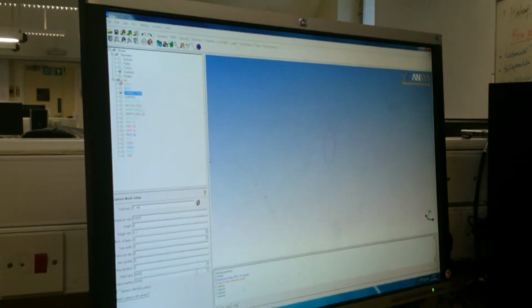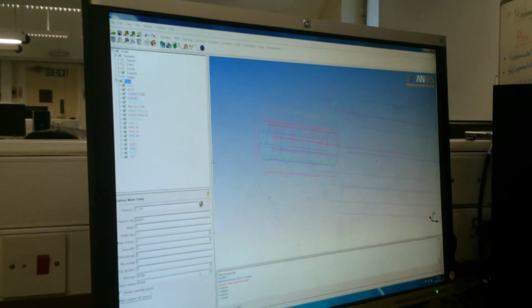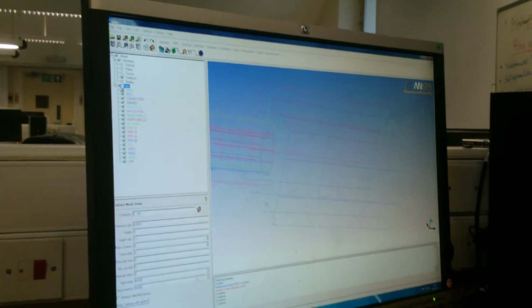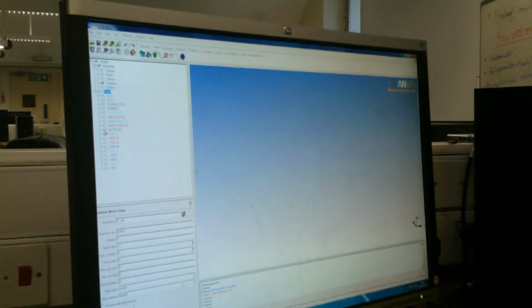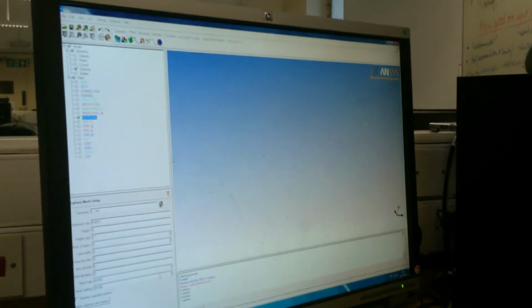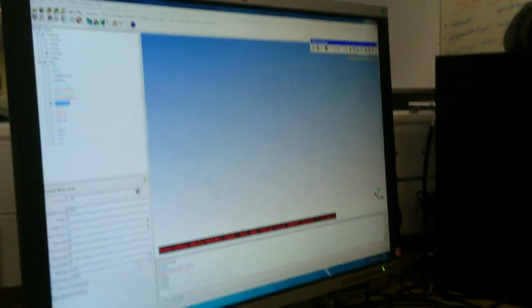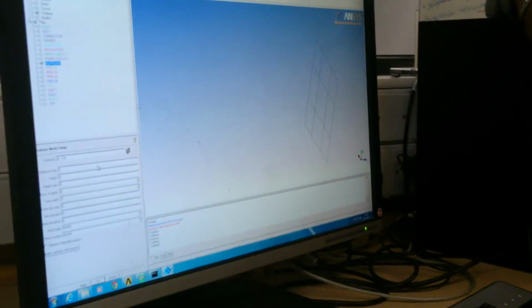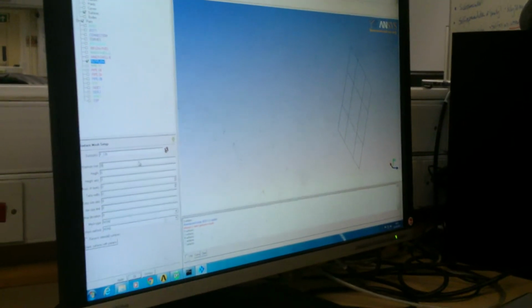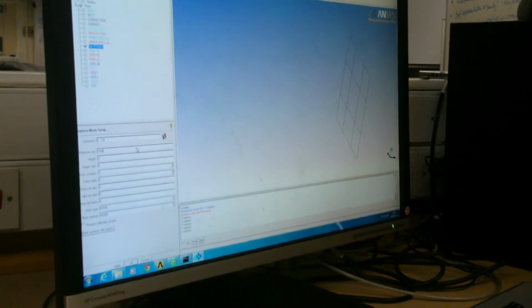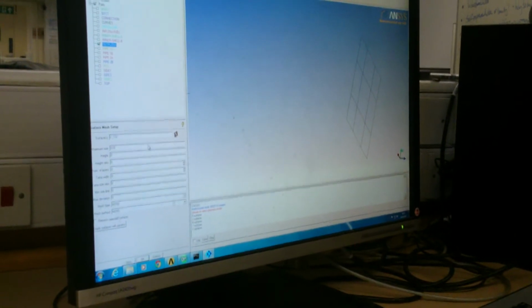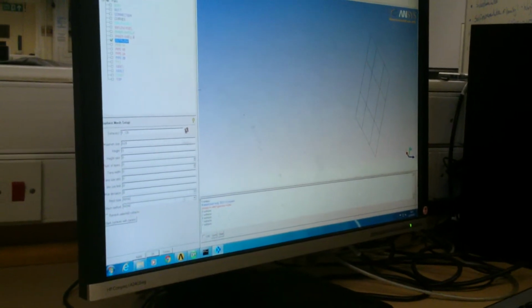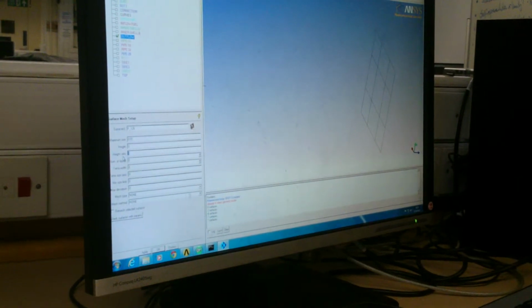What else have I left? Even the outflow, give it a slightly better mesh. So, do you remember the largest one is how much? 0.015, right? So I'll give it 0.01 and 1.1.